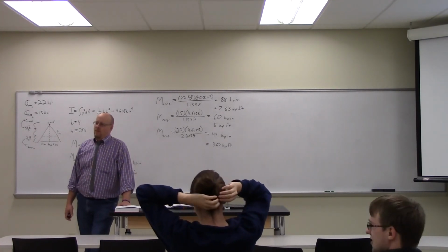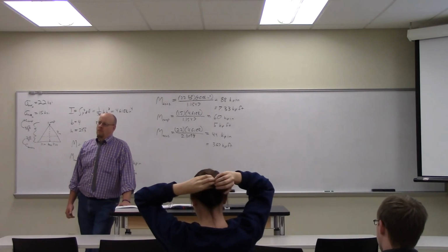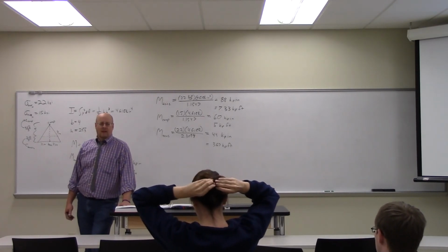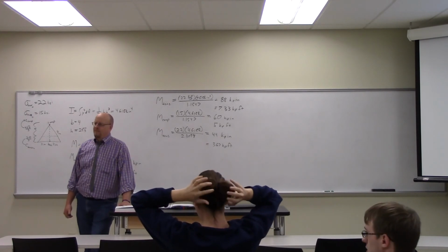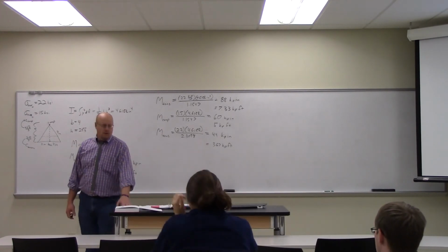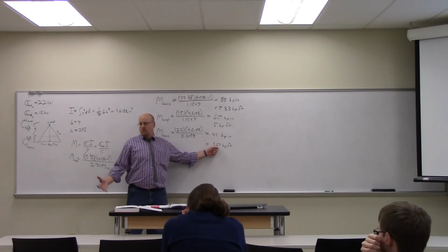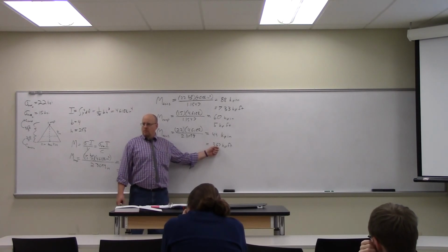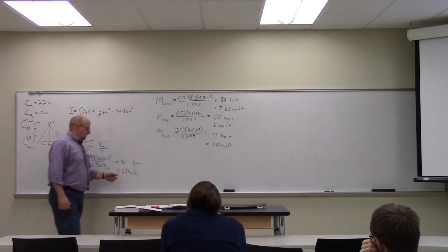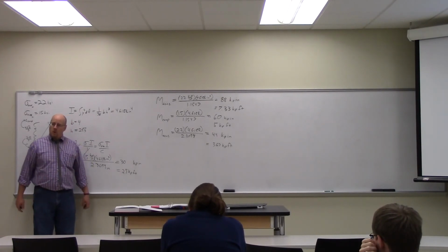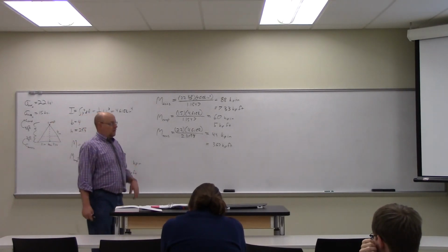Okay, and so when you bend it down with the corner pointing up, that's stronger than bending it up? Which one's stronger? Bending it down or bending it up? Bending it down is stronger. It takes 3.67 kip feet of moment to get it to fail bending it downward. It's 2.5, a much smaller moment, to get it to fail bending it upward. Okay. All right, look at the second problem.